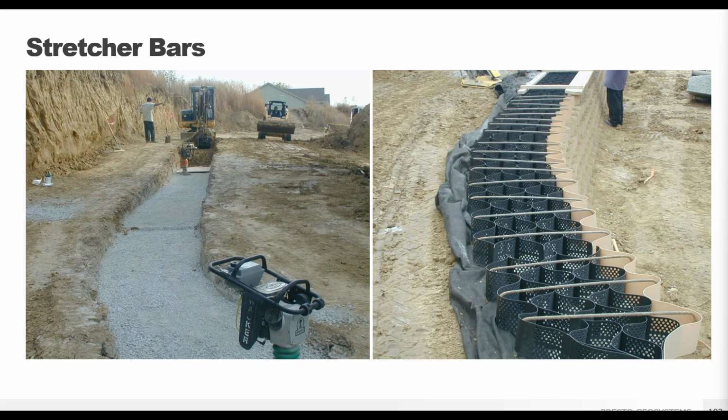When your wall has to curve beyond a gentle turn, stretcher bars are a best practice as they'll hold the wall cells open to that optimal expansion while making the consistent curve radius needed. Note the portable compactors to compact the foundation layer.